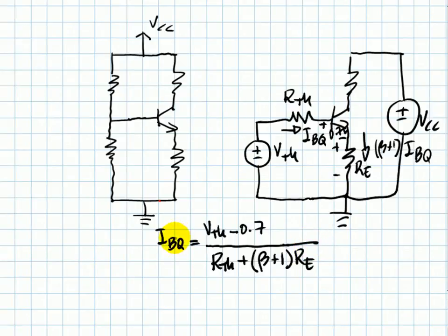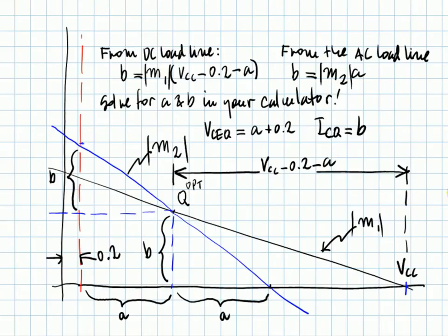Nice formula. And from there we just multiply that value by beta to obtain this current, ICQ. You see how fast and simple that is, just finding the Thevenin equivalent of what is on the left. Let's move on to the next question. So here's the next question.